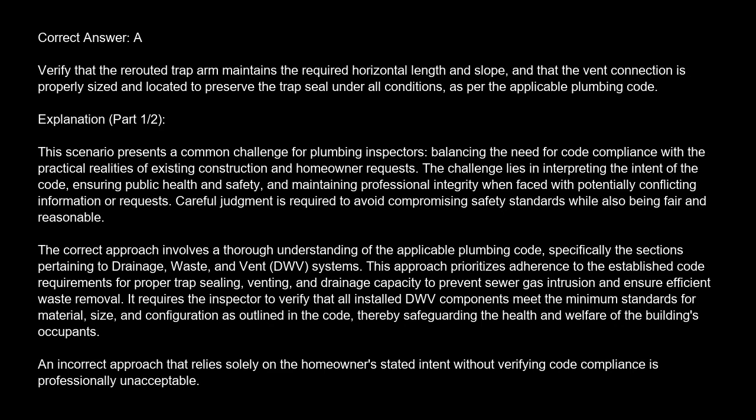The correct answer is A. Verify that the rerouted trap arm maintains the required horizontal length and slope, and that the vent connection is properly sized and located to preserve the trap seal under all conditions, as per the applicable plumbing code.